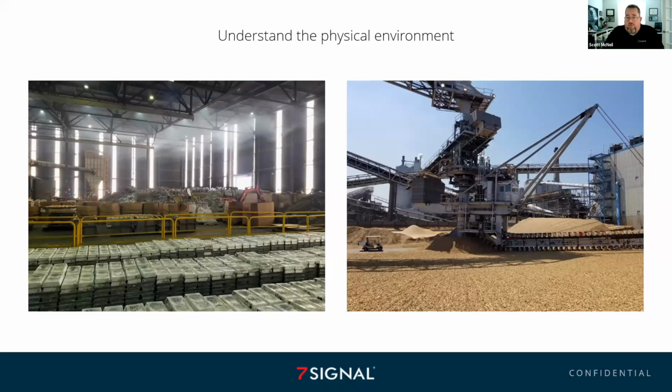So now you have full-on weather exposure: sun, heat, rain, wind, cold. On top of that, you're going to have to take into consideration the vibration of this equipment. So when you go back and you're trying to spec out hardware for this, you're going to have to really do your research and make sure you're finding the right mounts, using the right radios, what's going to be able to handle vibration of that caliber that you may not have seen if the only thing you saw were pictures, as opposed to actually going on site and climbing on this thing. So there is no substitute for going on site when it comes to industrial wireless deployments.